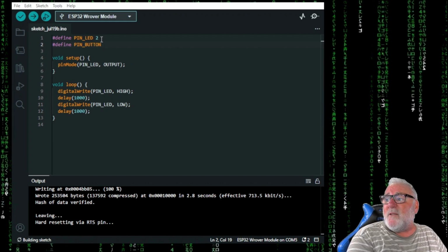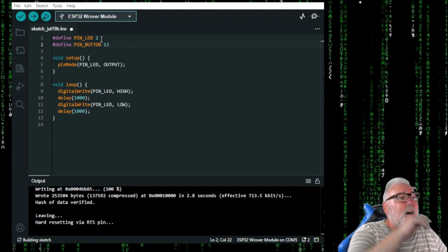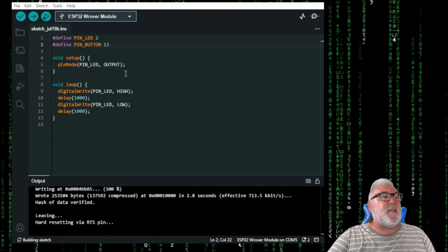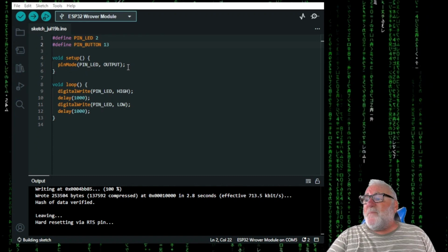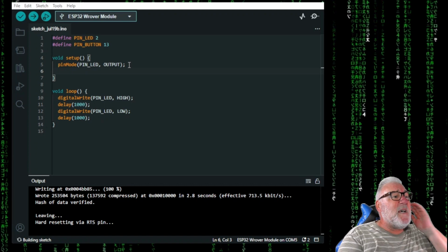Space, sorry, no space, yeah, space 13. Okay, so we just put our button on pin 13, haven't we? All right, now we need to come to what we want to happen once. So it's pinMode.